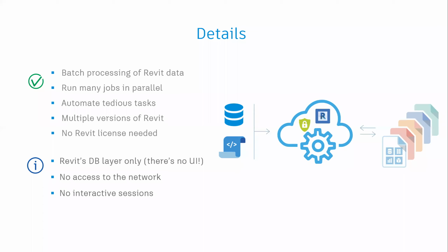Other really important details. First of all, this is Revit's database layer only. So there is no RevitUIAPI.dll. So if you have applications that are using that DLL, that's not going to be available to you. The reason, simply put, is that there is no UI as part of the service. It's just the data layer.